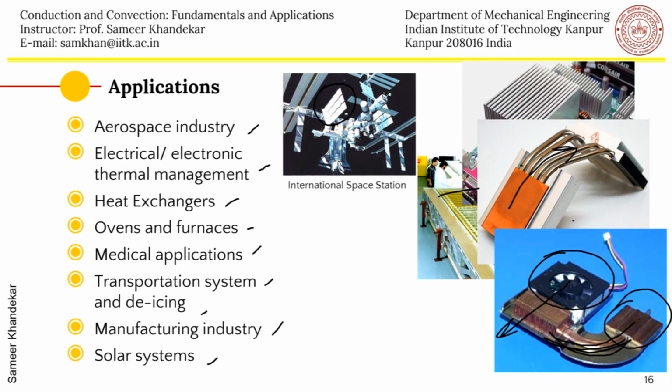Here again you see an IGBT cooler, 3 heat pipes, 2 of them bent and 1 of them straight. And again you can see this is a very small area where the heat is collected from the IGBTs, and then it goes to the large area here.